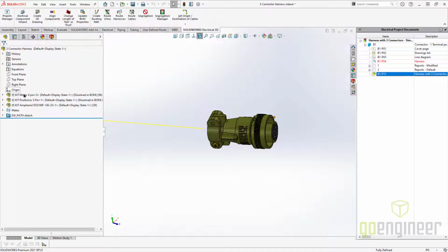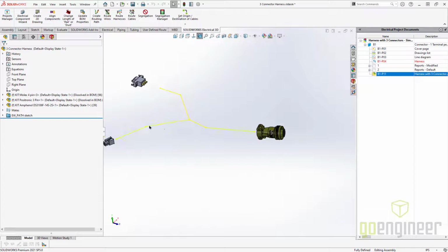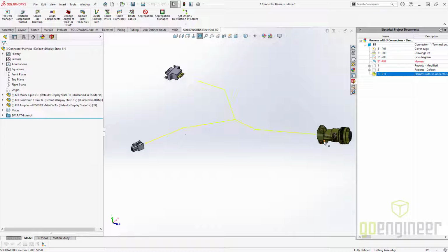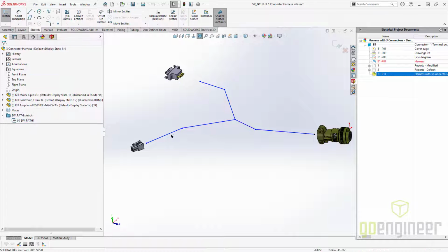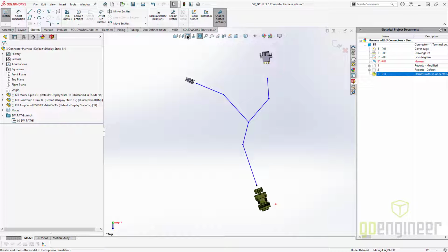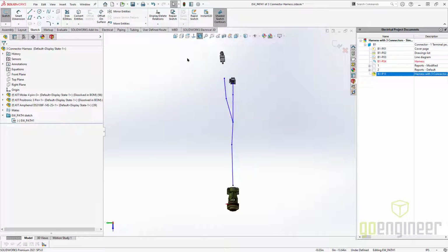So I've associated parts within these 3 sub-assemblies. I've also created a 3D sketch inside of my assembly. The 3D sketch, if you haven't done 3D sketches, a good recommendation that I always like to do is work from standard angles. So switch to the top view, only work from the top view. And then you can use the Shift and arrow key to rotate to 90 degrees. And then you can look at it from the right view.